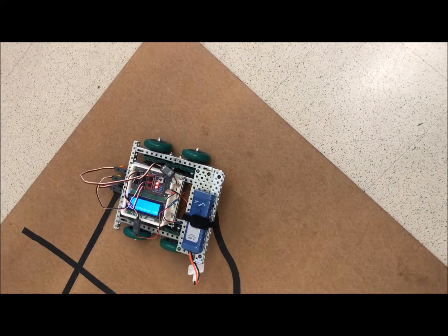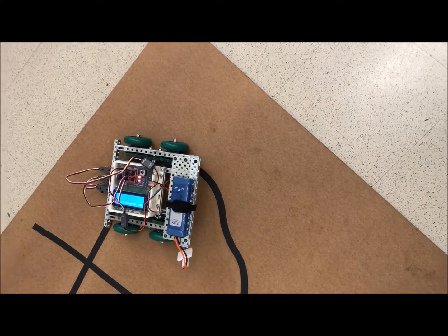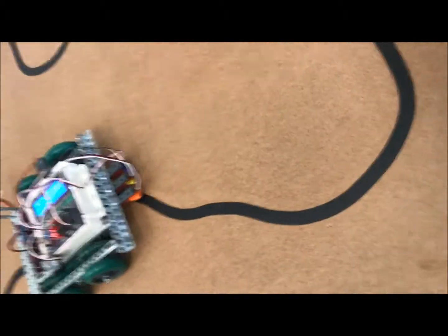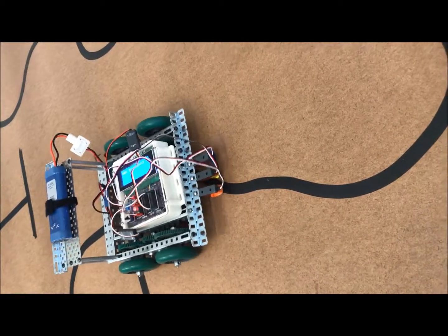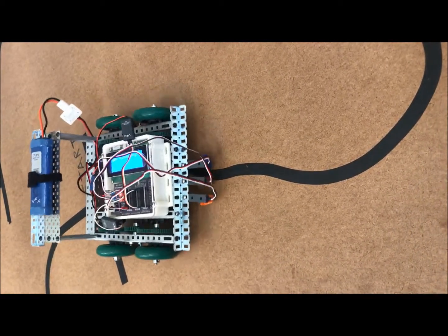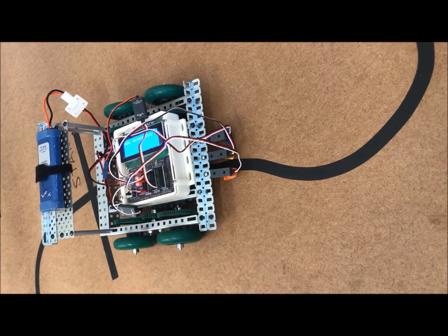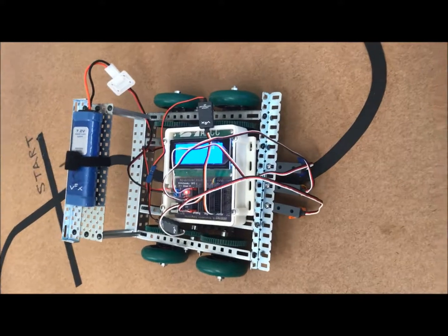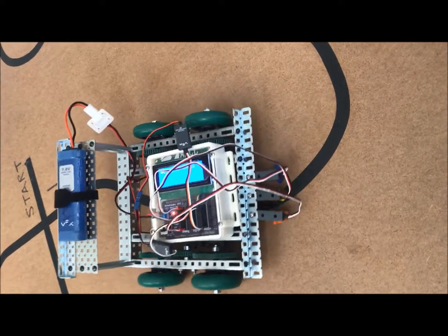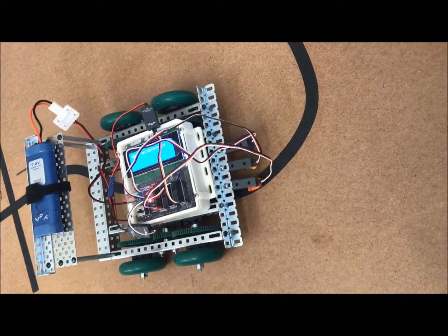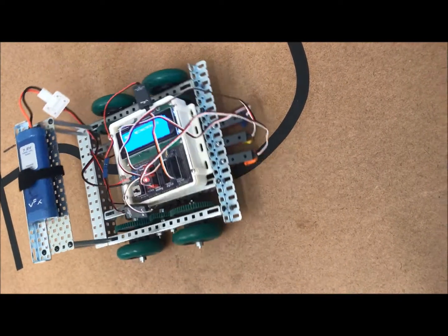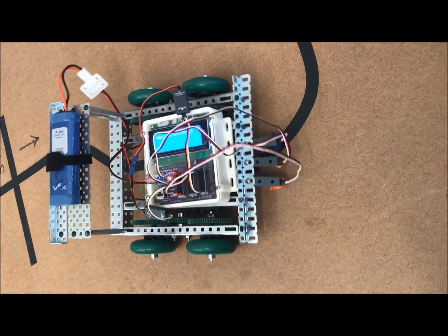Another thing that I definitely should have done, which is probably the biggest issue that I had, was to switch from 4 wheels to 3 by removing the back axle and basically just replacing that with a free spinning wheel. By doing that, the robot's turns would have been much more accurate. Especially with 2 axles, when you're making those very intricate turns, it's a lot easier just to handle 2 wheels up front, and then just have a free spinning wheel in the back.